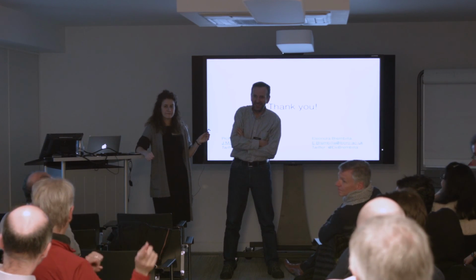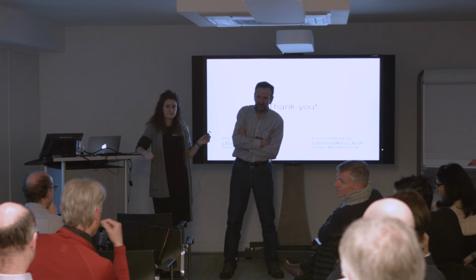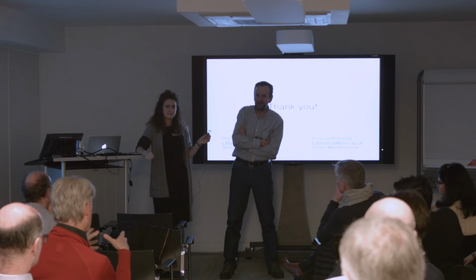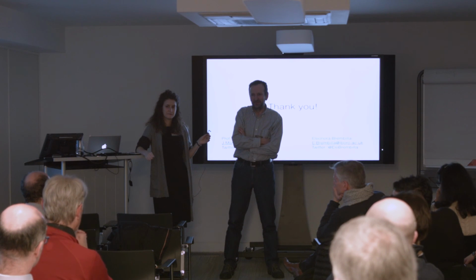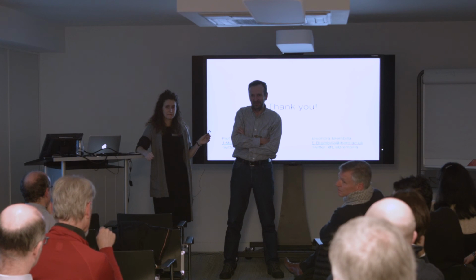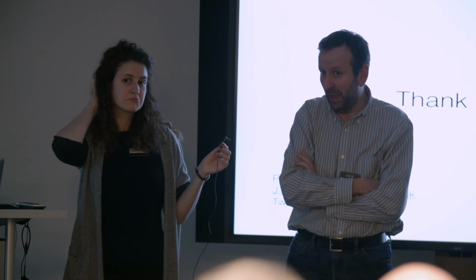Can I summarise Eleonora's presentation for myself for a moment? So long as I'm not trying to do what I've always had difficulty understanding in the IES North American documentation, the annual sunlight exposure measure of potential for glare, the simplest method that I can use, and therefore the fastest, is going to produce as reliable a result as the more complex method. If you do it well, yes, that would be. So long as I'm not trying to put in BSDFs and all sorts of modelling of complex fenestration, which the simpler methods don't allow the possibility. All the comparison was done for clear glazing anyway, so yeah.